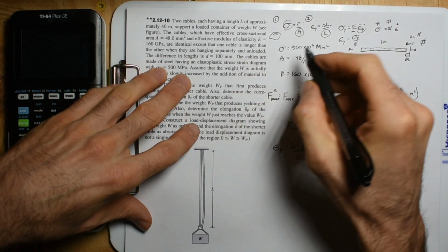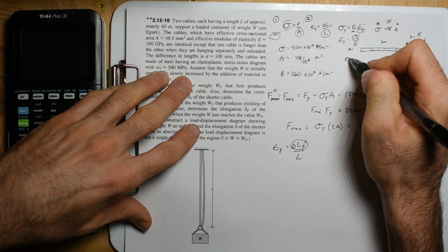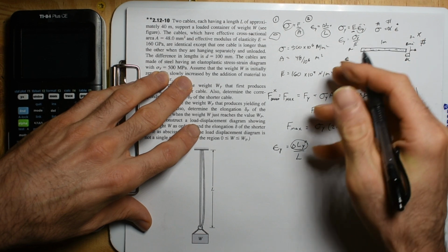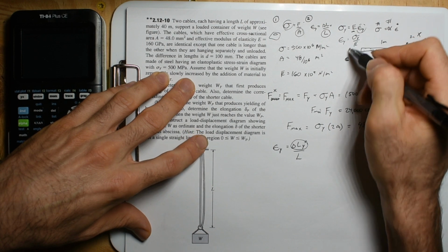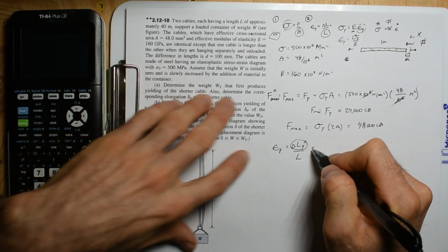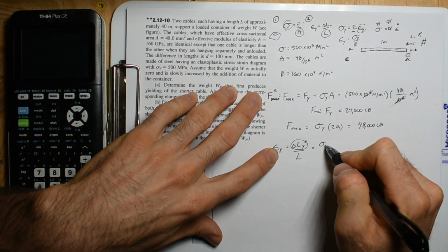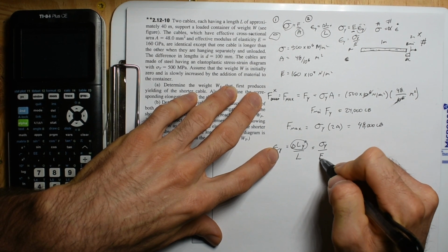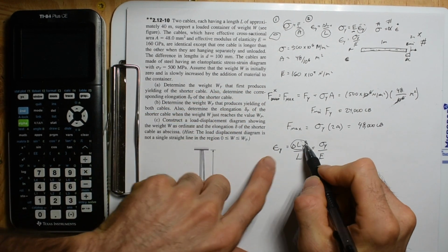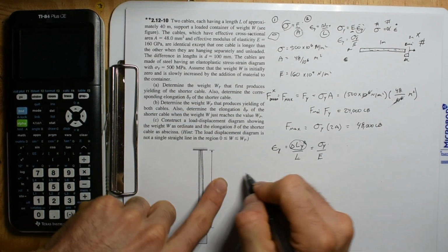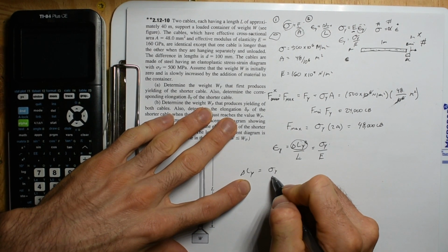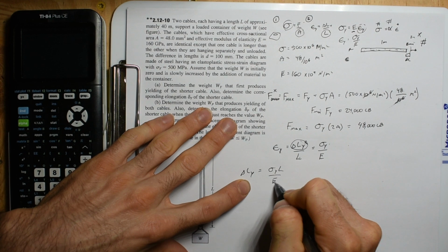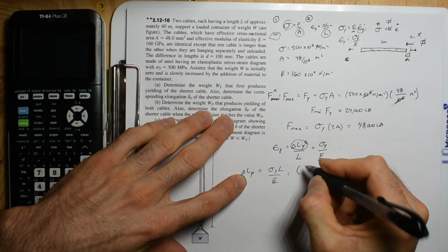Typical equations won't give you this strain value, and it's kind of a bummer. They just won't spoon feed it to you. You have to do some work to get it, or you can just bypass it by throwing in that this is going to be strength over area. So now I can solve for this, bring the L upstairs, and I can go change in length yield is equal to strength yield times length divided by E. So now I can just write all these in.